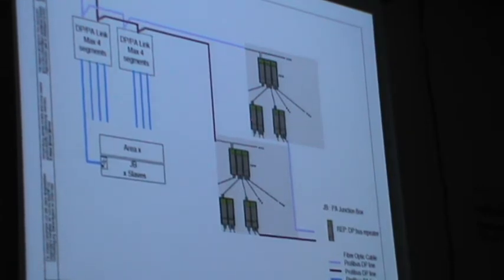But here one thing is you cannot measure anything from this cable using a multimeter. Only the voltage will be available to power on the transmitter. To power on the transmitter, the same cable is used, and to get the signals from the transmitter also the same cable. You can measure only the voltage. You cannot measure any 4 to 20 milliamps from the transmitter using your multimeter. These are all Profibus instruments. You cannot use your multimeter to measure what value is coming. It is only available from the DCS.